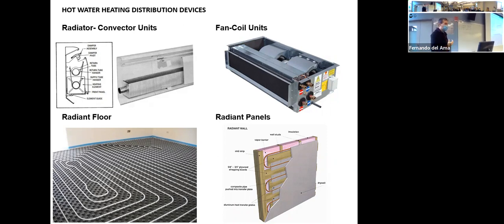So that's the difference between fan coils and air handling units. If you look at fan coils, they look like this. There is no difference. And I can tell that this is not a fan coil because we have refrigerant fluid. If there was water, it would be a fan coil. If we have refrigerant fluid, it's a split unit with a heat pump.